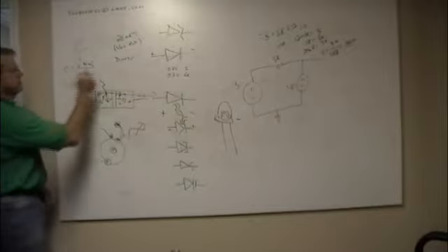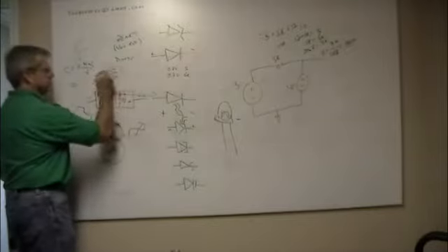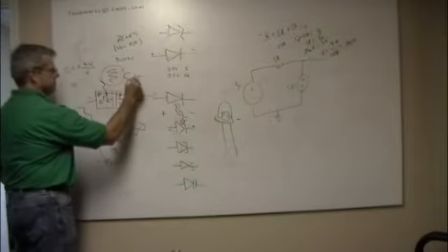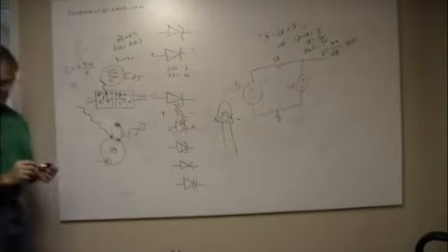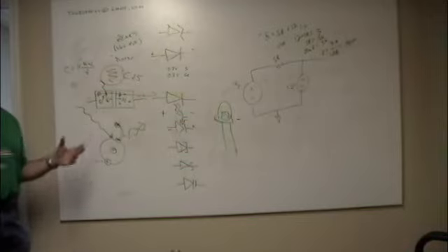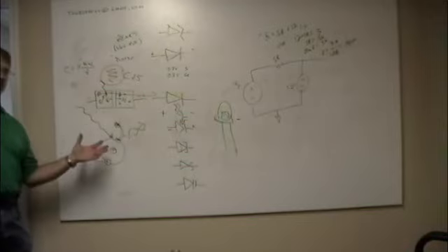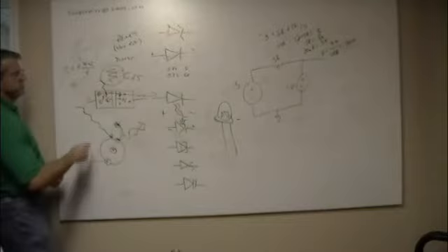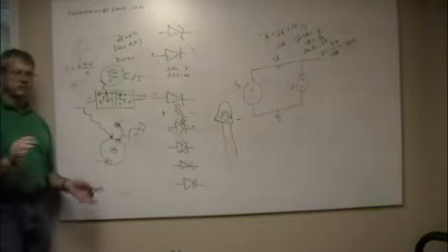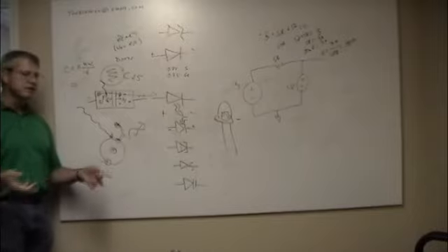The one that you're talking about that has the little grid on it, it looks like this, it's usually round. Yeah. That is cadmium sulfide, CdS. And that is a change in resistance. So they might change from 100 k ohms down to 10 k ohms under varying conditions of light. What you see with these is more and more current flows. So depending on how you're using it, it can have a similar effect.